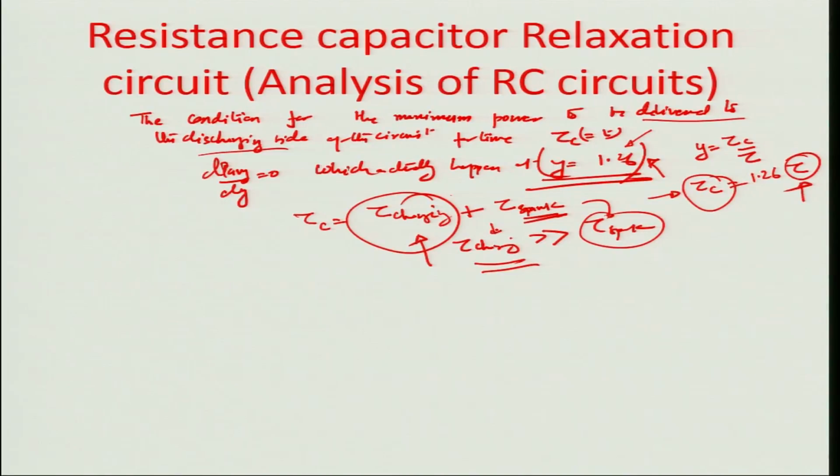Okay. So if I want to do that here in this particular case, I would get a very different kind of situation. So let us say Tc is actually the charging time, the time in which the capacitor charges to the full extent, and so I can actually get the value of Vct, which is the voltage across the capacitor as a function of time, and it has been earlier calculated as V0 times 1 minus e to the power of minus t by the time constant tau of the RC circuit.